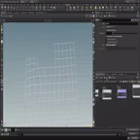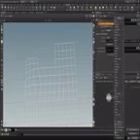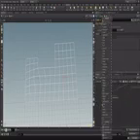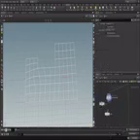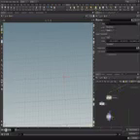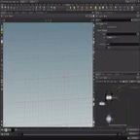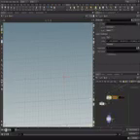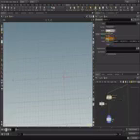There we go. And now we place down an add node and a sort node. First wire in the add node, and let's remove geometry with key points and do it by group and by attribute, and the attribute is prim ID, or wait, what was it? Yes, it was prim ID, which is supposed to be a point attribute, so this needs to be a point value. Luckily we can just simply change this to be a point value.